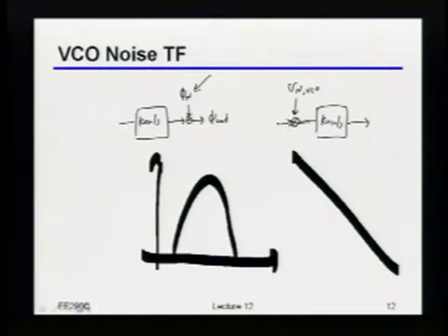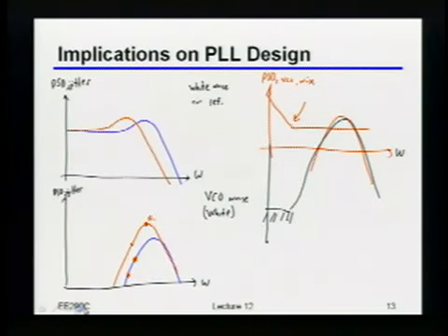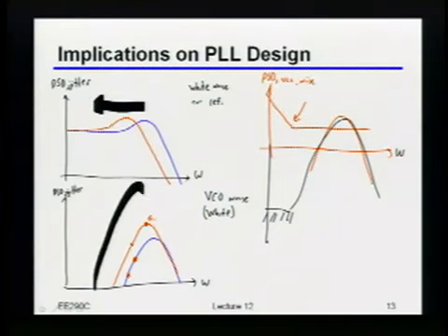Okay, so now, we spent actually more time on this than I expected, but that's great. You guys asked lots of questions. There's kind of this trade-off here that really should hopefully be obvious now, right? Which is that if I really had a lot of reference noise, then what I want to do is push this curve as far to the left as I can, right? But notice that as you push that curve to the left, you're always going to be pushing this other curve up and to the left, right? In other words, as you try and filter the reference noise more and more, the noise you get from everything afterwards is going to increase, right?